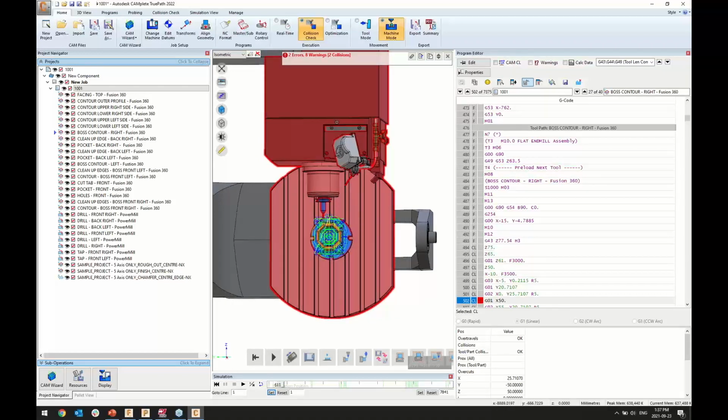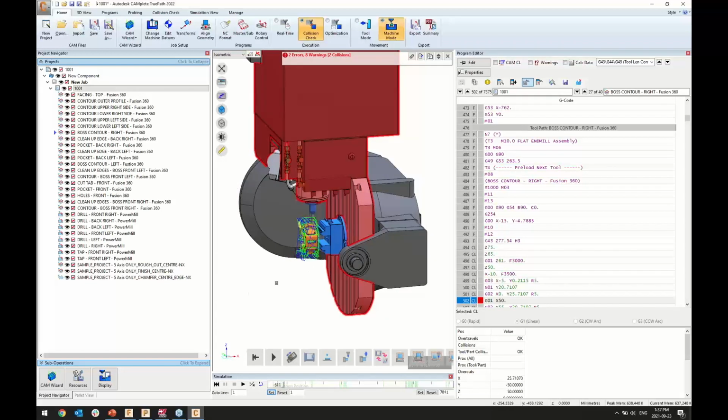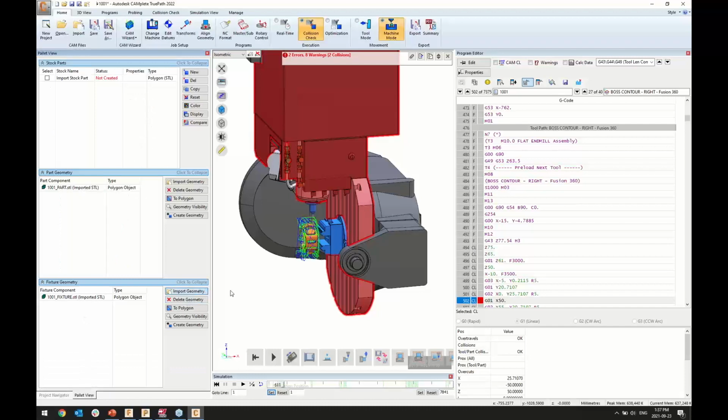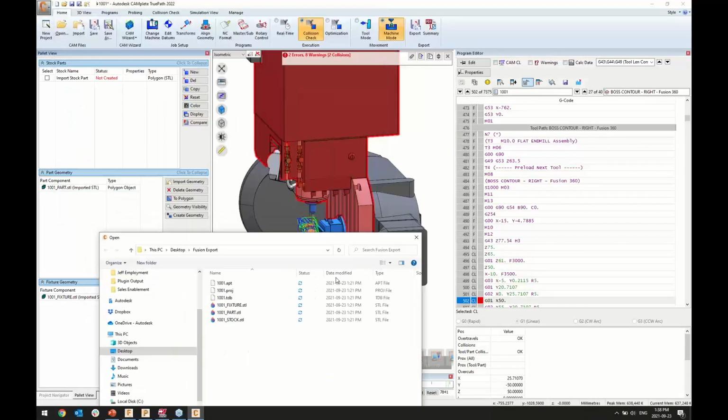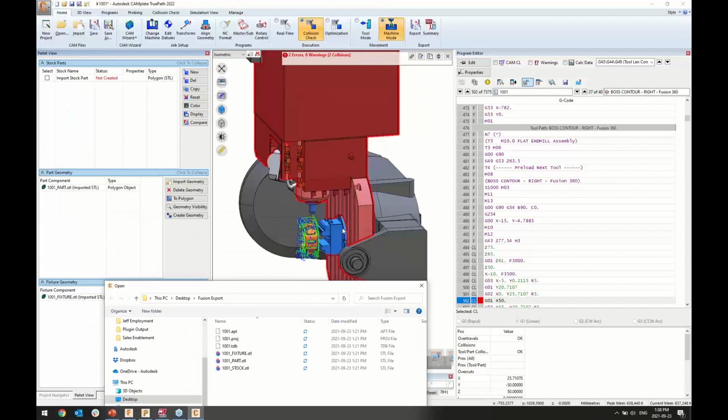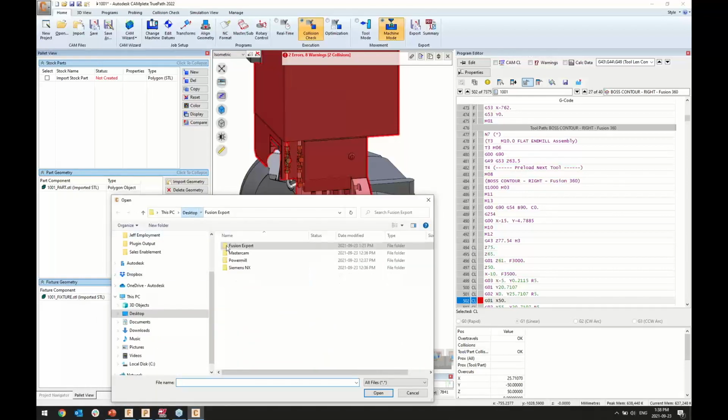machine is not symmetrical. I have a long side and a short side, so it may just be a setup question as to how the part itself is oriented when it gets clamped on the table. So we're going to very quickly go through those elements and then quickly jump back onto the presentation. So at that point now I can import, for example, a riser that I could add onto my fixture. So adding the riser will add a little bit of height onto my fixture and hopefully enough that we can clear that collision. So in that case, I can grab that riser from NexGenCAM.